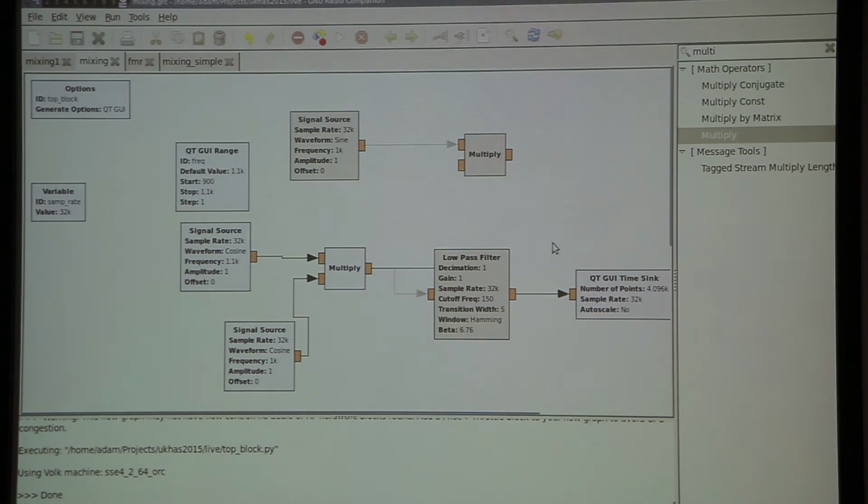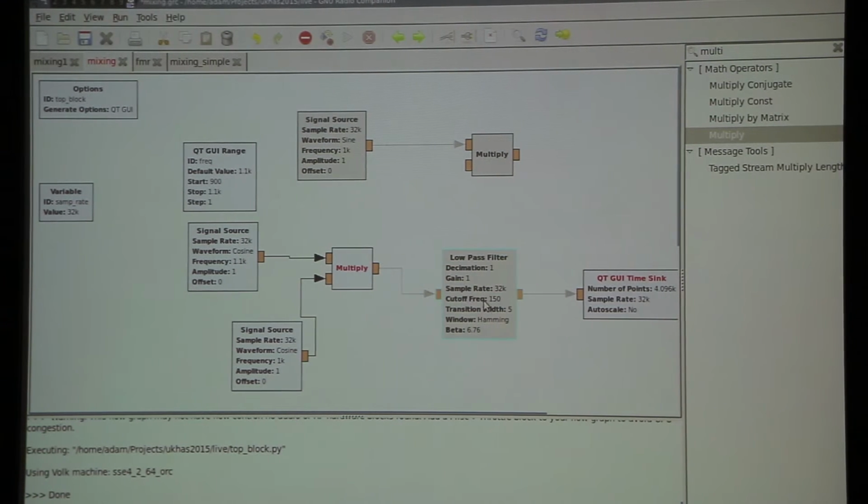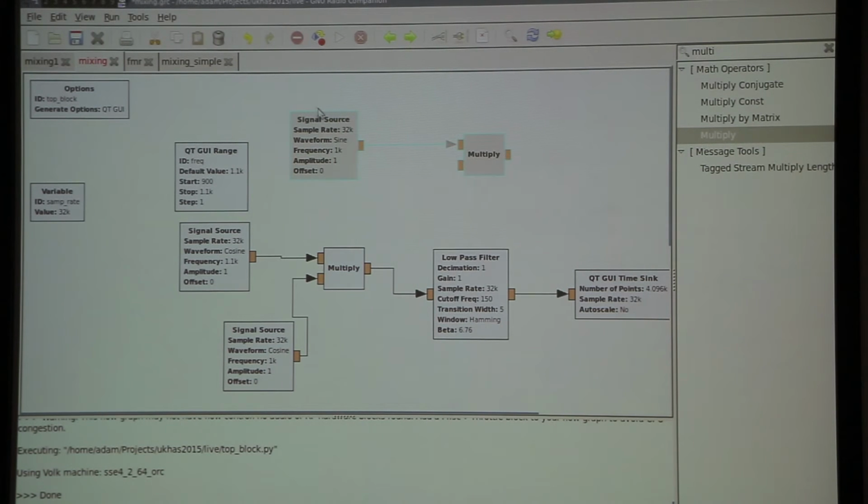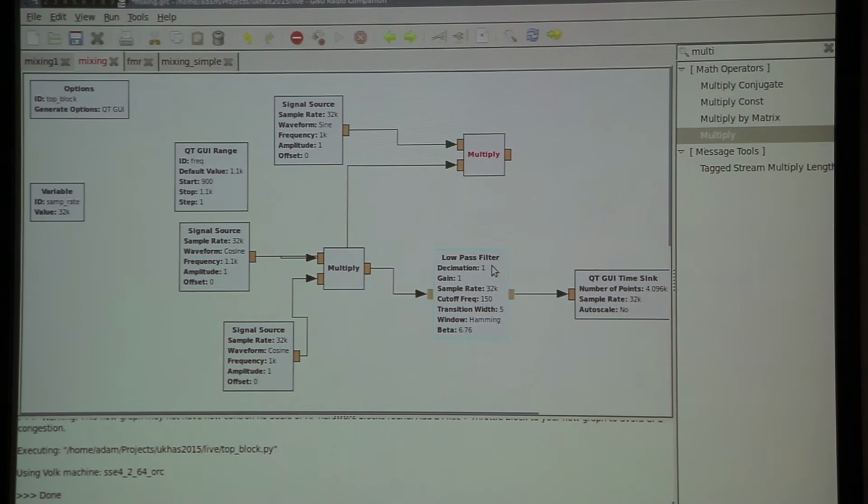If you can think back to trig identities at school, this is because 2 cos A cos B is equal to cos(A+B) plus cos(A−B). Right, so it is a thing that happens to be true, which is quite nice for this. So I'll turn this back on. Take the signal and multiply it by our new local oscillator. Copy the same low-pass filter.